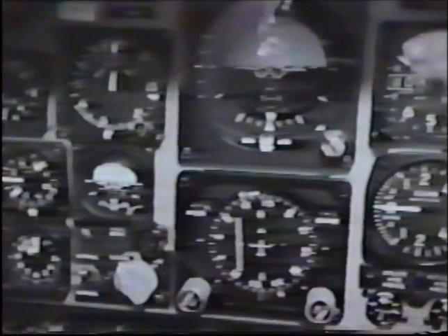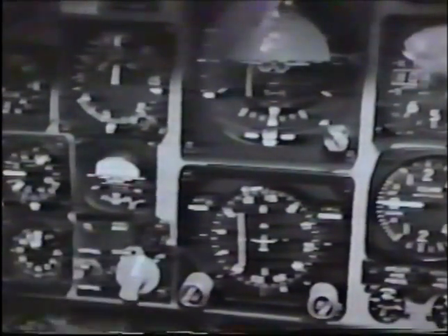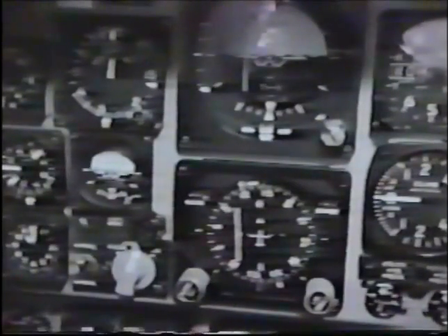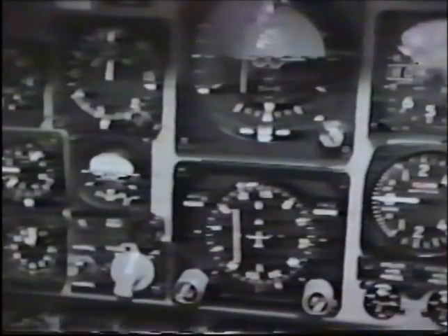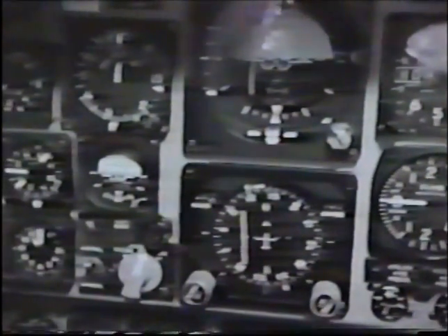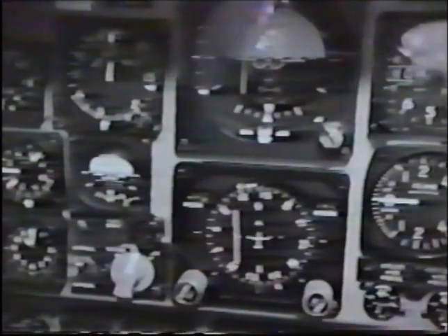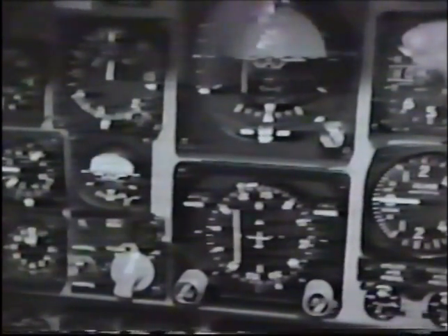Now you want to check your ILS. To do this, make sure you have the ILS frequency for the departure runway set in your ILS receiver. Next, select the localizer final approach course in the course select window and select the localizer on the nav mode switch. Notice that the bank steering bar comes into view on the main ADI and that the CDI shows your relative position to the localizer course. A warning flag at 12 o'clock on the ADI would indicate that the localizer signal is insufficient for this check.